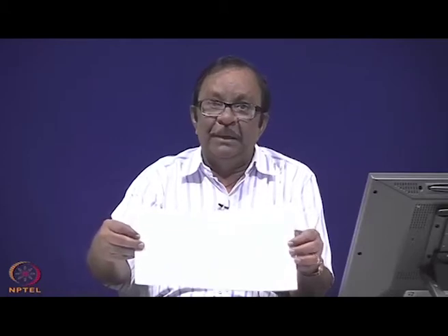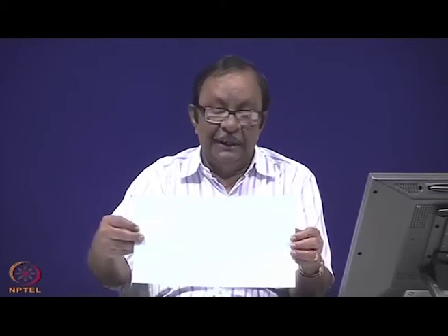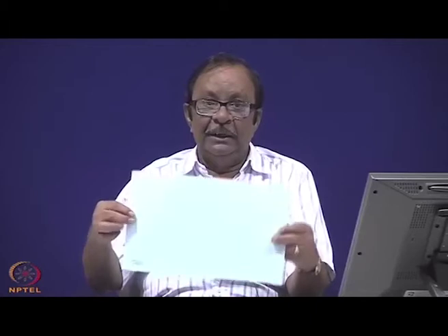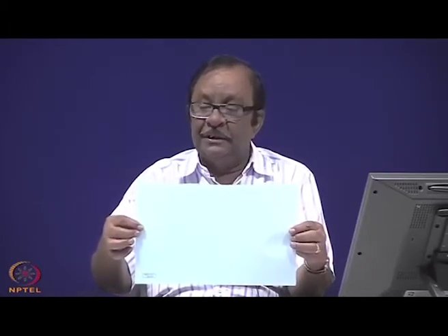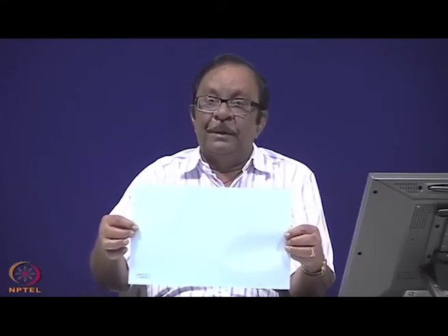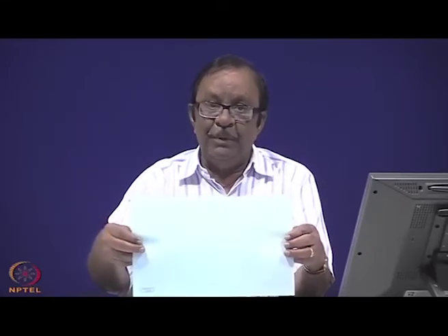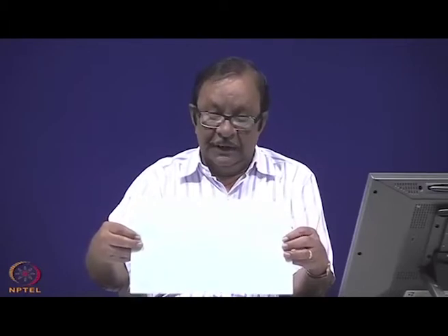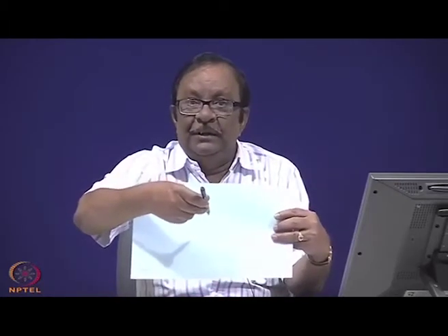Okay. So, it becomes nearing horizontal in summer and nearly vertical in winter, depending upon of course, the latitude. So, the idea is this is the aperture plane, to my left is the east, to my right is the west, and then I will tilt it like this, change the slope of this plane such that the sun's rays are normal to the plane at solar noon, something like this.